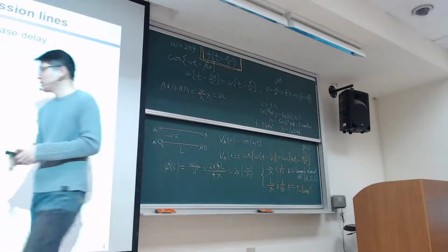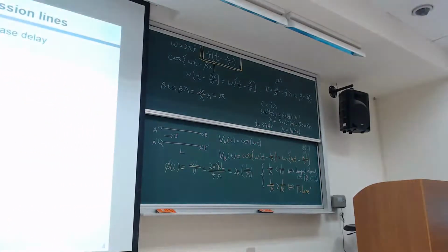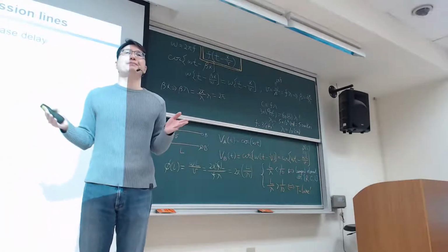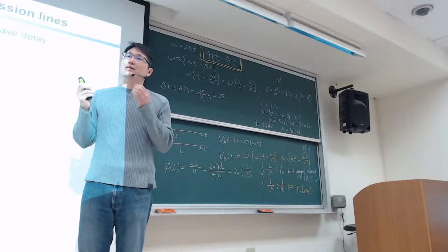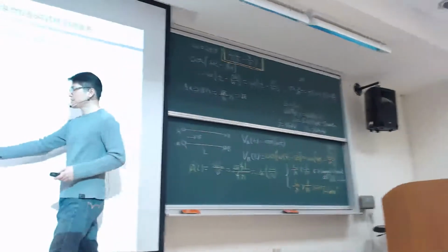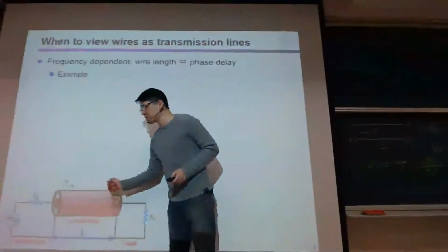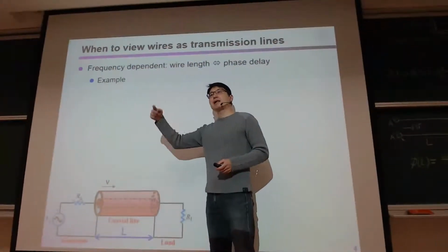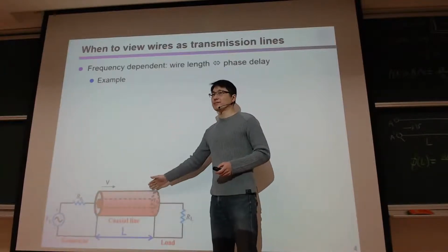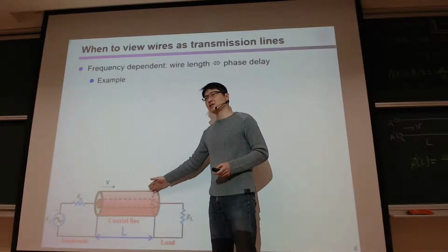And on the board, this length is about 60 centimeters. Oh, that's very long, right? So everything is frequency dependent. Even though you are using the same two wires, just depending on your frequency, sometimes you need to view them as transmission lines.